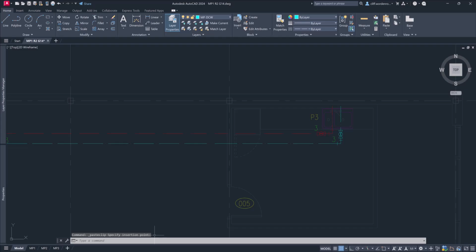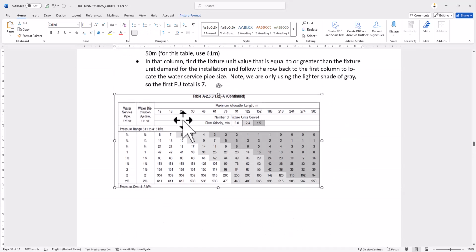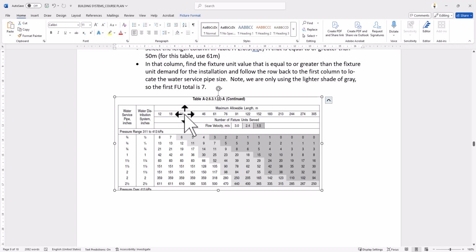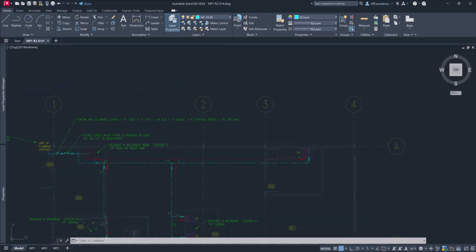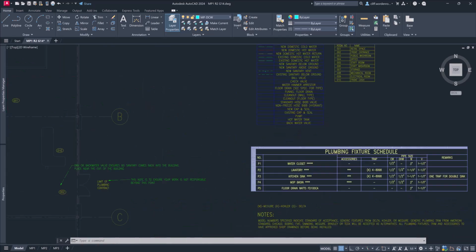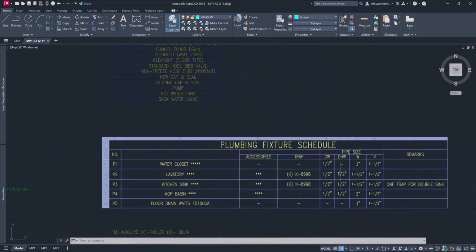Okay. So we're going to go, again, circle. You go here. The hot water, cold water system, again, is the same. And even if you had one fixture, which was the cold water that was the furthest away, you can still use this table for that developed length if you wanted to. All right. So once you have your developed length, you can stick to it throughout the whole calculation. So here we're going to use this one. So 24, 6, 1/2 inch.